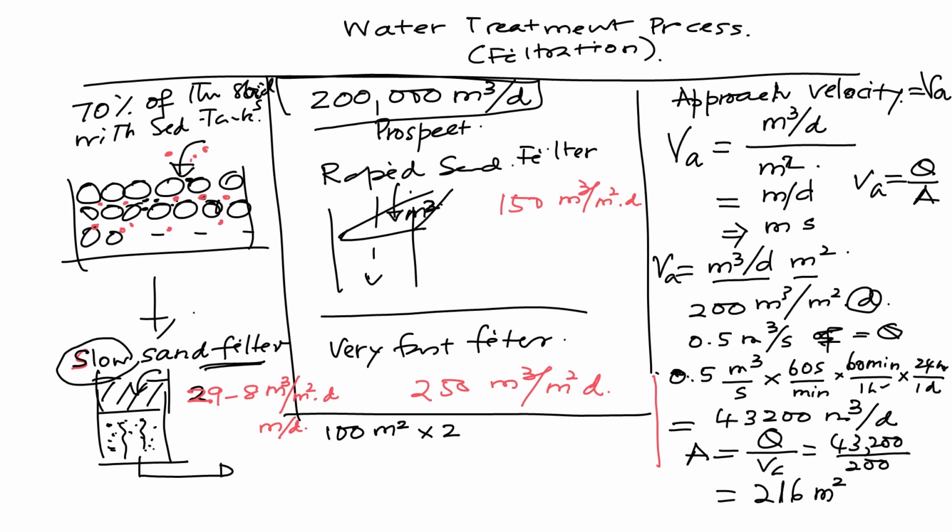That is the issue. Now any water treatment plant has to have at least one filter not functioning. In case one of the filters is not working, or if you want to do some maintenance in one filter, you have to have one filter all the time available for you to do any repair there, and still supply the water to the customer.